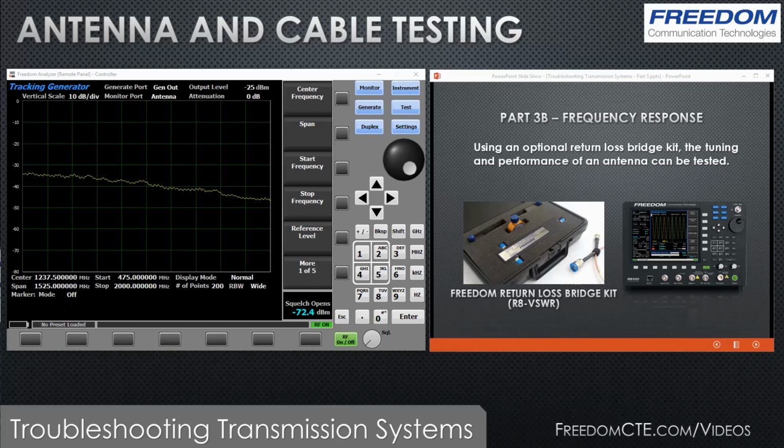At this point, we've swept the cable and antenna and determined whether or not there were any problems to be investigated along the cable. Let's make the assumption that we didn't find anything, but we're not getting a very good return loss measurement at the end of the cable, indicating that there's a problem either at the connection or that the antenna is not tuned properly, especially for the frequency that we're operating at. So now we want to look at the frequency response of the system to try to determine if perhaps the antenna is not tuned properly or has been damaged in some way.